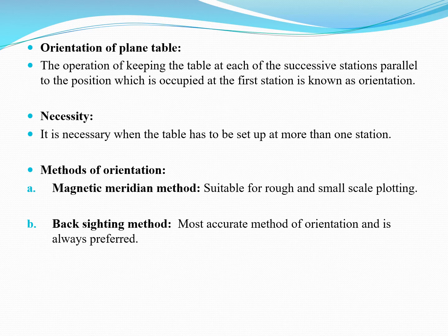After that, the trough compass is placed at the right corner of the sheet to mark the north direction, with reference to the north-south direction of the trough compass. After that, with the alidade touching point P, a ray is drawn bisecting the ranging rod at Q, and the line PQ is drawn by a suitable scale.